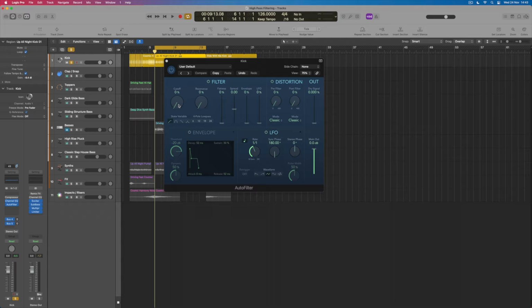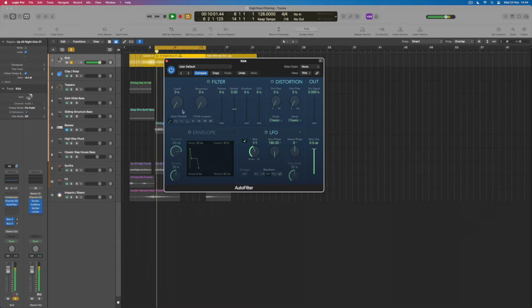Now, because the dial is all the way across to the left-hand side, you can almost imagine this being bass content. As we come up towards high frequency content, scrolling the cutoff dial around to the right-hand side, what we're doing is omitting or getting rid of all of the bass frequency content that exists between the extreme bottom end, the super low bass frequencies, and increasingly up to high frequency content as well. So if I play that sound and we sweep the cutoff dial through, what we'll find is that we get this slightly disembodied sound as we roll out the low end of the sound.